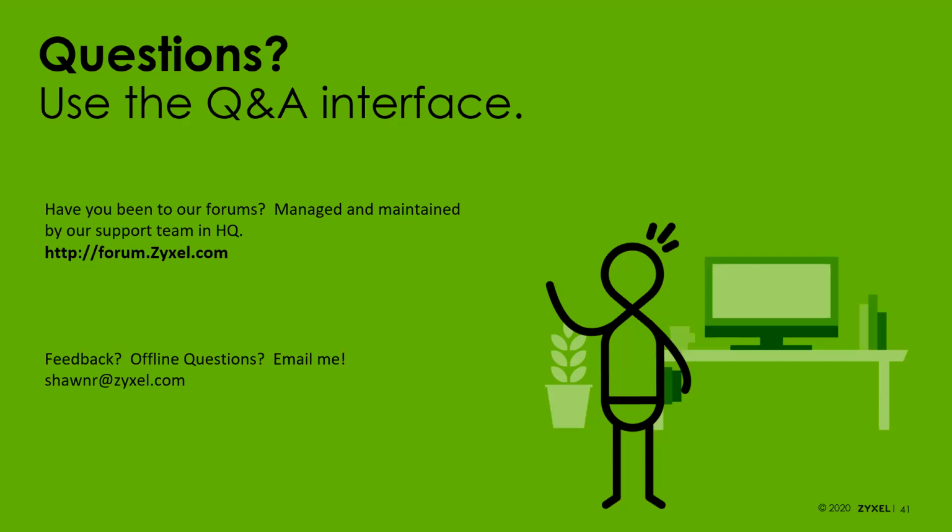Paul says here, you had charts on output power. Can we add receiver sensitivity or is that too hard to get? It's out there. I know for our products, if you pull up the data sheet, we always have the sensitivity on our data sheet. It's just not something people generally are asking for, but it is there on the data sheets. And in general, when we do these comparisons, generally the receive sensitivity isn't that different between the different vendors, at least what they're putting on their data sheets. Most of us are going to generally be in the 99 to 103 range. So I hope that answers that question here.